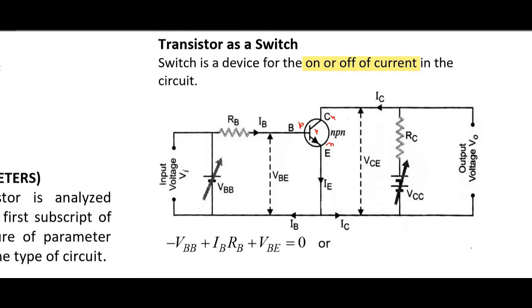Now we know this, always remember this formula. In many of the problems you will have to use this formula. And even if you have to make a quick calculation, you can put IE approximately equal to IC, because IB, the base current, is in microampere.